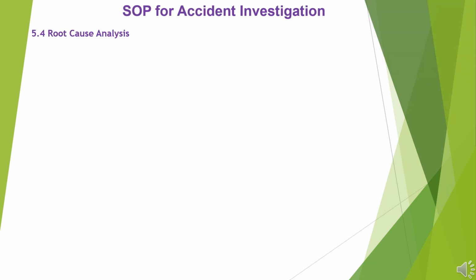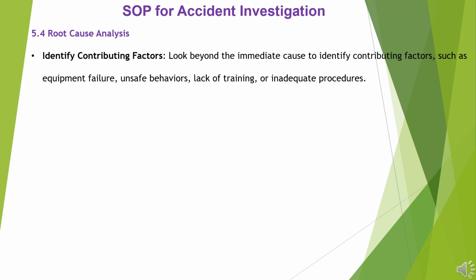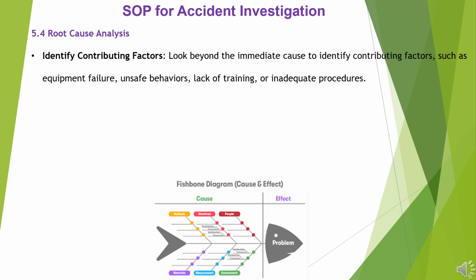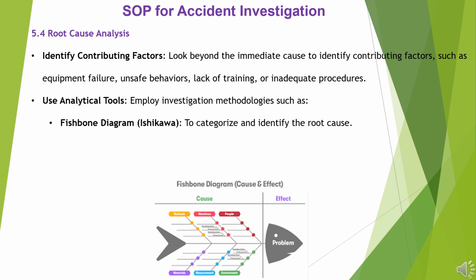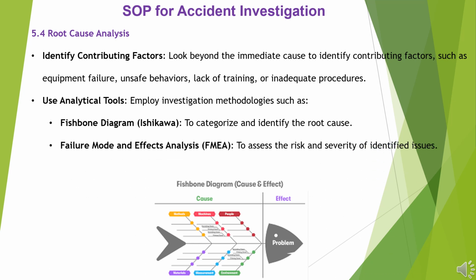5.4 Root cause analysis. Identify contributing factors. Look beyond the immediate cause to identify contributing factors, such as equipment failure, unsafe behaviors, lack of training, or inadequate procedures. Use analytical tools. Employ investigation methodologies such as fishbone diagram, Ishikawa, to categorize and identify the root cause. Failure mode and effects analysis, FMEA, to assess the risk and severity of identified issues. 5 Whys, to ask why repeatedly until the root cause is identified.